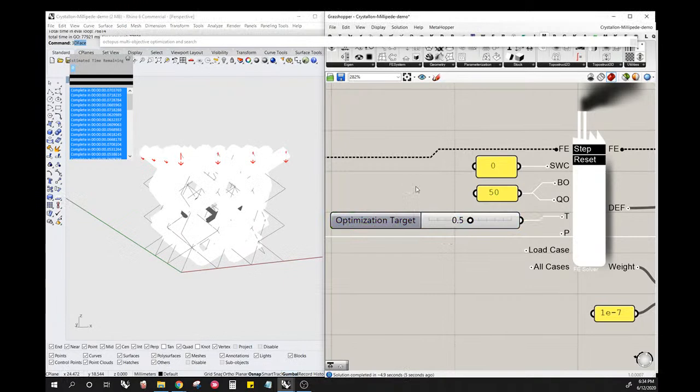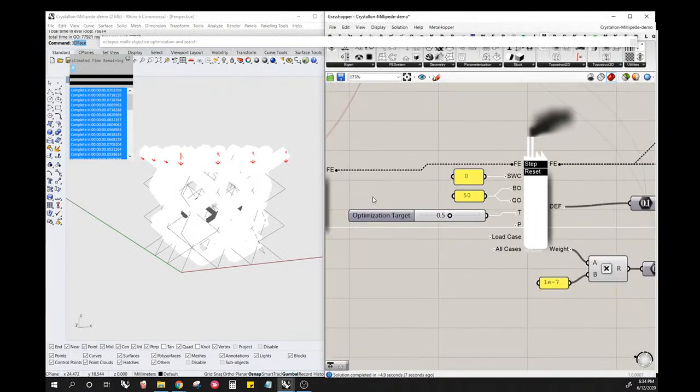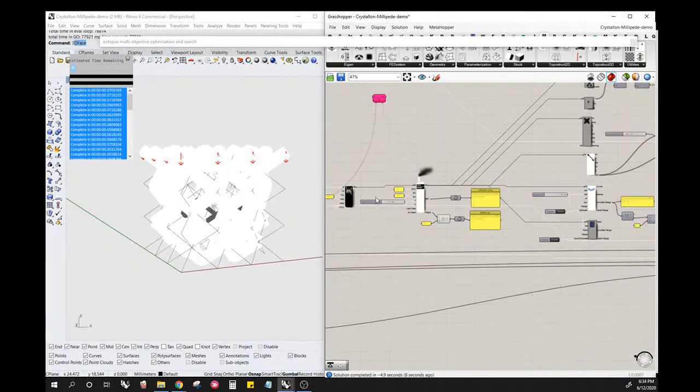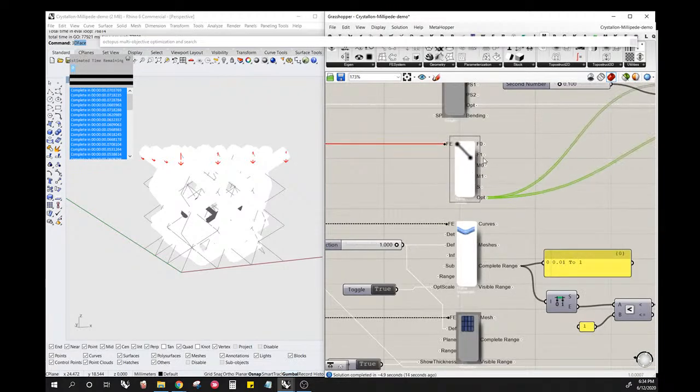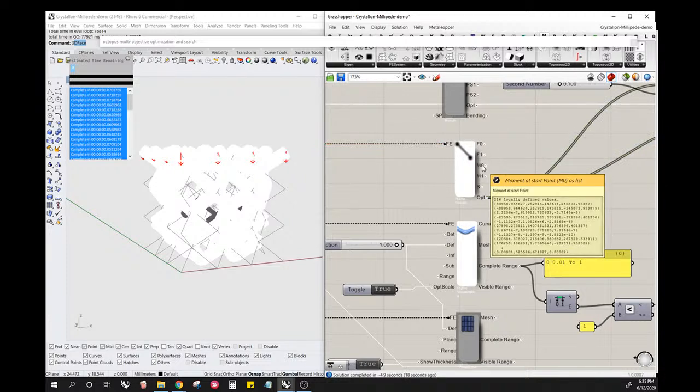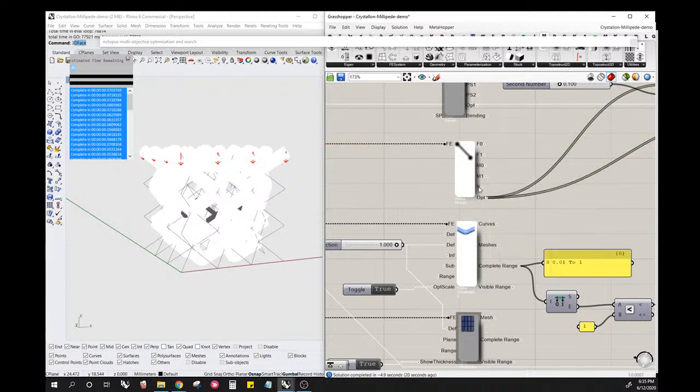And so how we actually use these results is what's most important, because the data we get, if we look at all our results from our beams, we have our forces, our bending moments, estimated max stress for each element, and then we have this stiffness multiplier, and this is the value that it's given that beam, and it's just a number from 0 to 1.